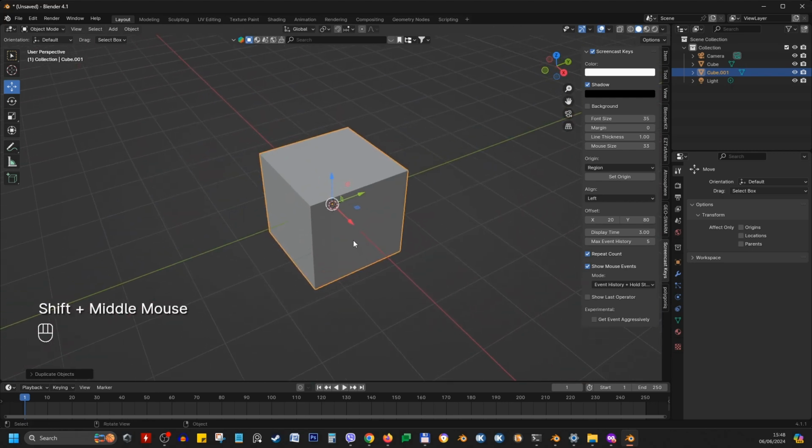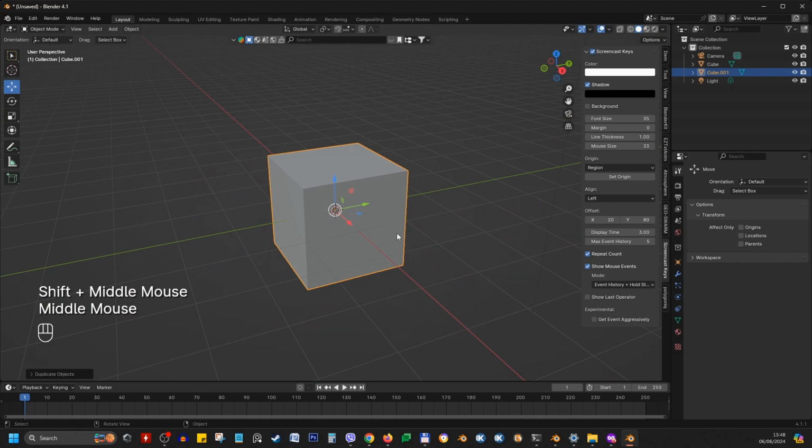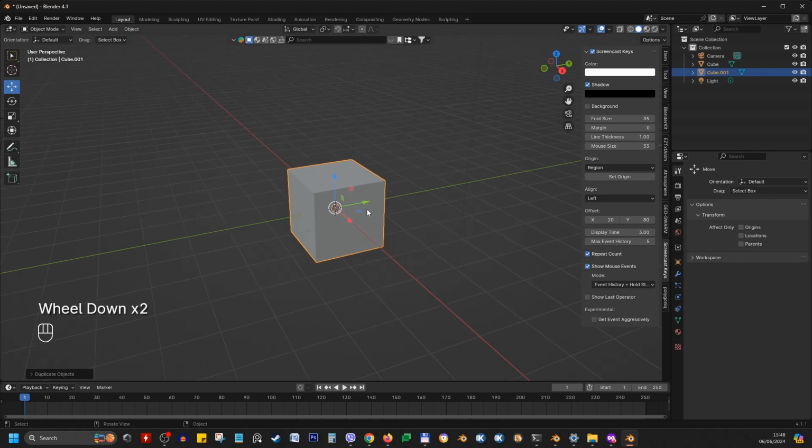And we don't really know which one we're seeing because they're exactly in the same place. So it's a good idea to either move it or not forget that it's there. Because double geometry in the same space can cause problems with texturing later on.